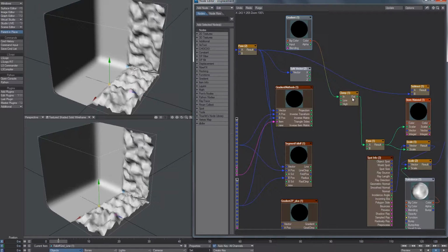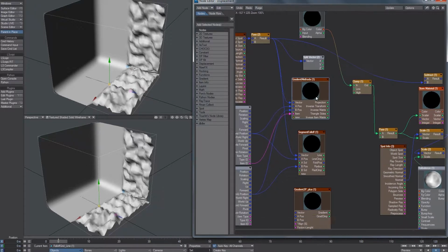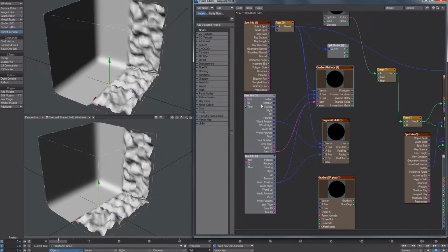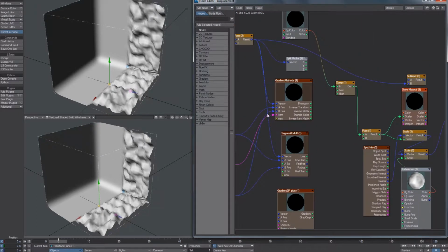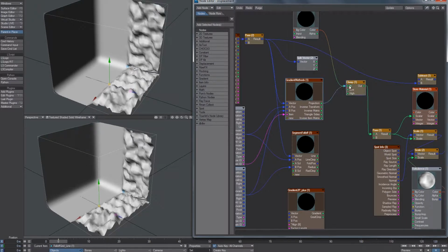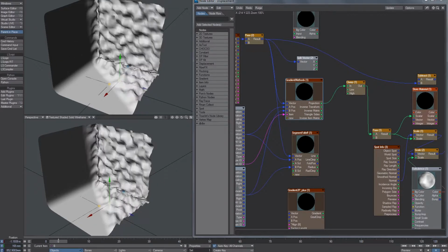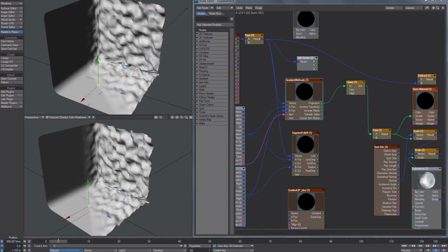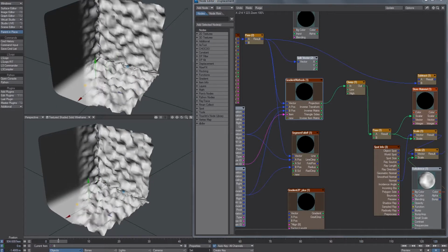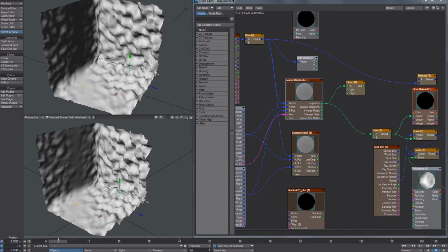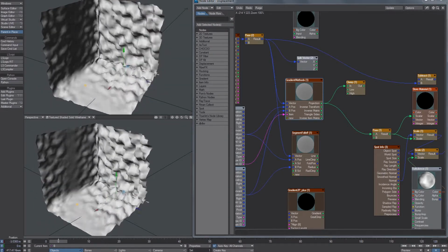So the first thing that I want to look into is how to have a gradient between two arbitrary positions. To talk about that, I have this gradient methods compound that I take in the object spot here in the vector, and then I take two objects, object A and object B, to control the falloff. So if I just connect this one in here, you see that right away I can have these two objects A and B to define a linear gradient. In this case, A will be the 0 and B will be the 1. Of course, if I don't clamp this, I'm going to get some extrapolation and the values will go a bit wild. That's why that clamp is in there.